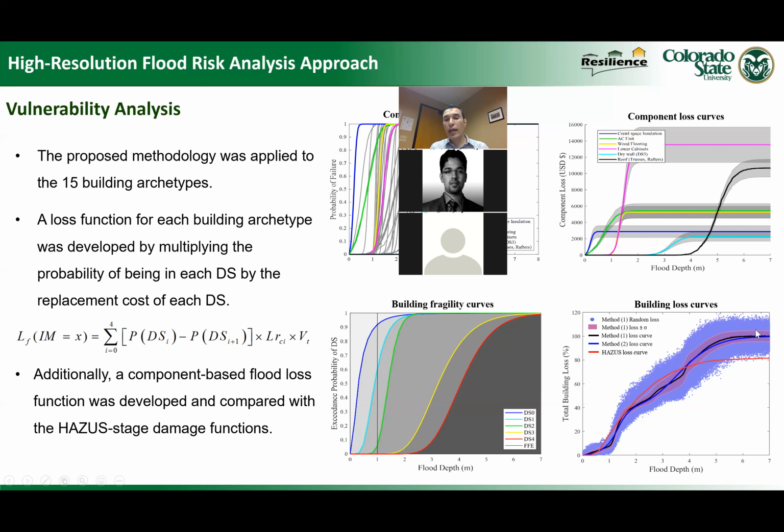This is because Hazus assumes that if the building was fully submerged with water, the structure will be there and it can be used. But our assumption is, if the building is fully submerged with water for a certain duration, we will be losing the structure due to many structural consequences, like foundation scour, long duration affecting the wood itself and its connections, and something similar to that.